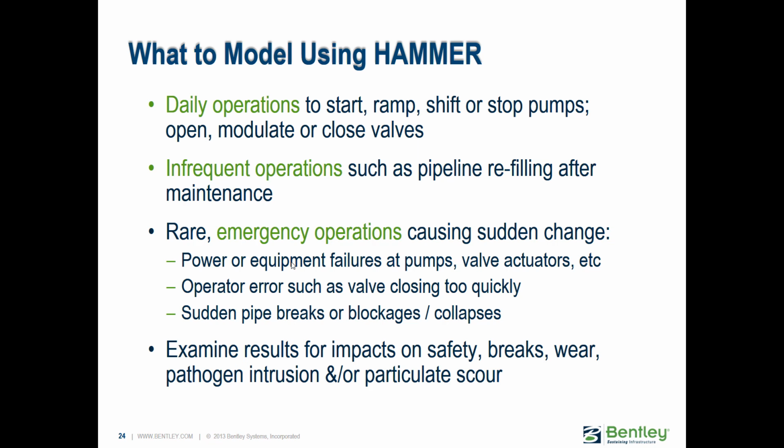And then you also want to be analyzing for those rare emergency operations, such as failure of equipment, emergency pump shutdown, valves failing in some way that causes them to instantly close, or operator error that could result in valves being closed too quickly. And then things like pipe breaks, which is very similar to opening a valve too quickly. You want to model those rare conditions as well to make sure that you've assessed if they will have a problem.